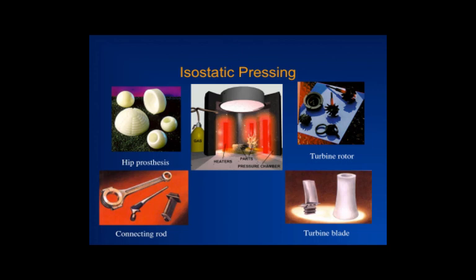And you can do it by isostatic pressing under heat, so-called hot isostatic pressing, as opposed to cold isostatic pressing, which is done at room temperature. So same thing, take some powder, apply some pressure. Depending upon the direction in which you apply the pressure and whether you apply heat or not, you have some variations in the type of component that's created. In hot pressing, instead of iso, it kind of tries to build the combination of advantages.